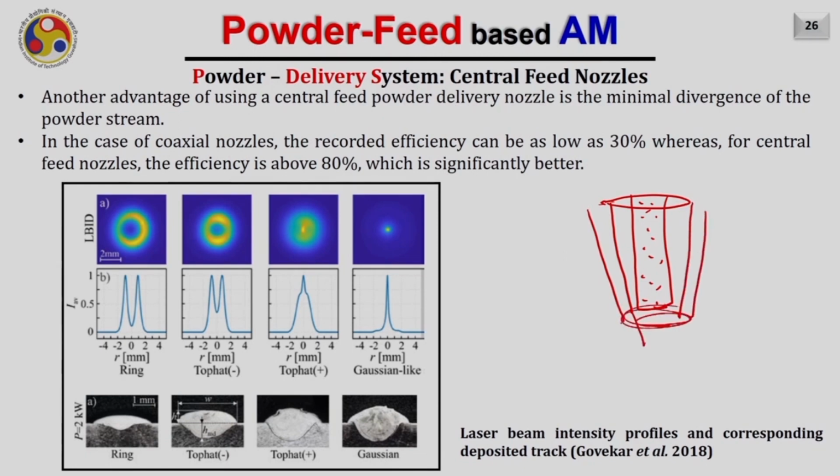And that of course reduces its diameter and gets merged to a small diameter as well. Now in that case, the energy is more available on the corners and at the center as well. As a result, the energy on the substrate is available quite uniformly in that case. So this is the typical intensity distribution of such a donut kind of laser at a particular height.